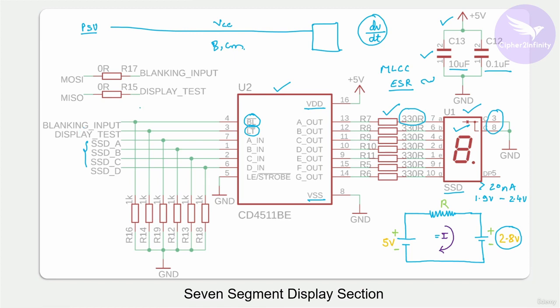We discussed that the IC we are using, Atmega 328, includes 23 GPIO pins. So you can choose any GPIO pin, whichever pin you like, in order to control these pins of this IC. It's not like you should use a specific pin; it's completely up to you based on your circuitry and the available pins in your microcontroller. You can select the appropriate pins to control these pins of this IC. Now, one thing that you will observe here is that I have connected these resistors here.